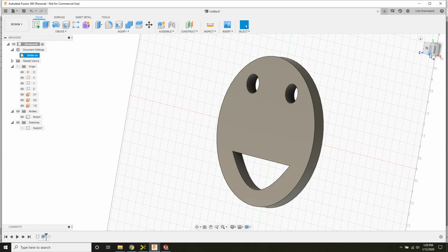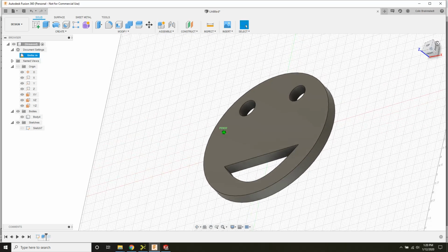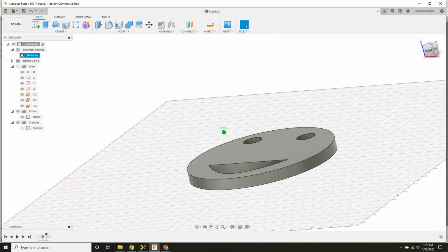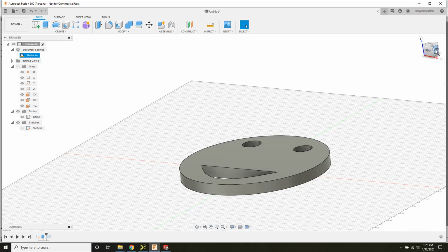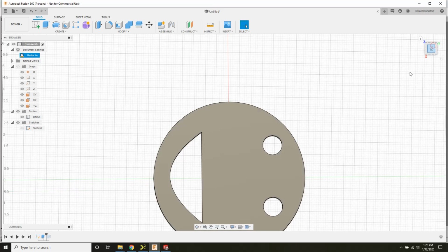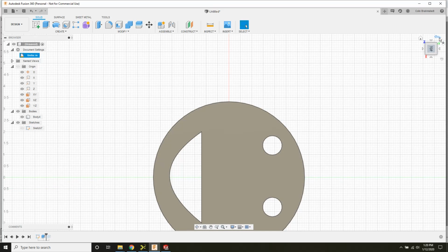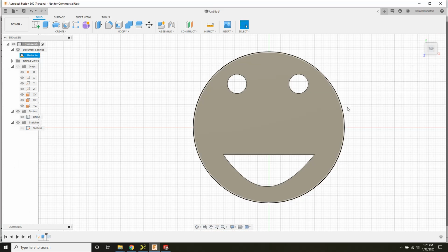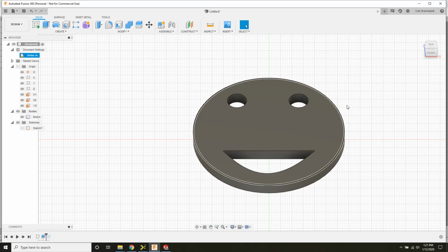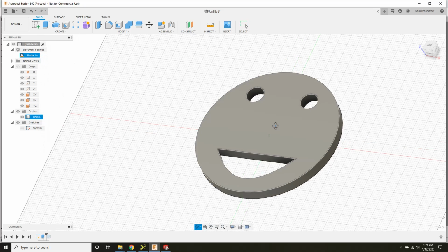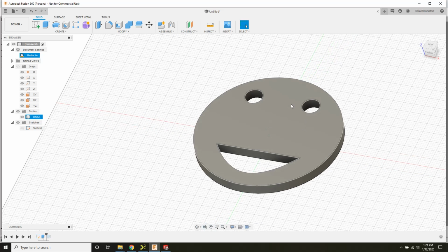Another way to do this is if you're working on, say, a trackpad, God bless your soul, you can move this little box around. So this little box, you can hit front, and you can get a front view of your object. If you hit right, it'll snap towards the right view. You hit top, it'll snap towards the top view, and these little arrows here will actually rotate your object if it snapped to the wrong view. You can also hit this little corner here, and that'll look at an isometric view of your thing. Hit this little one, kind of a bird's eye view. This is your God's eye. This is a bird's eye view. So yeah, that is your controls. Really annoying if you can't do that.